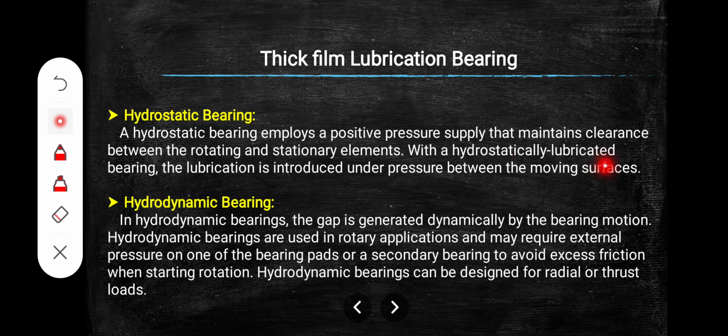With the hydrostatically lubricated bearing, the lubrication is introduced under pressure between the moving surfaces. As already said, in hydrostatic bearing there is a positive pressure supply. Here the positive pressure is supplied by another system, like a positive displacement pump, gear pump or vane pump, from which we provide the external pressure. Here the pressure is not generated inside the bearing; pressure is externally supplied.